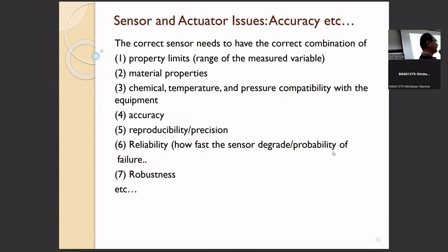Okay. Accuracy of your sensor. You use a thermometer, you use a thermocouple, you have a pH meter. You have to check the accuracy. That means how to check, how to calibrate. That means when you use it, you calibrate your equipment or not. The easy way to calibrate, you have to know the true property. That's right. You have the standard property. And then you check this equipment with the standard. Okay. This means the accuracy. They correspond to the true one.